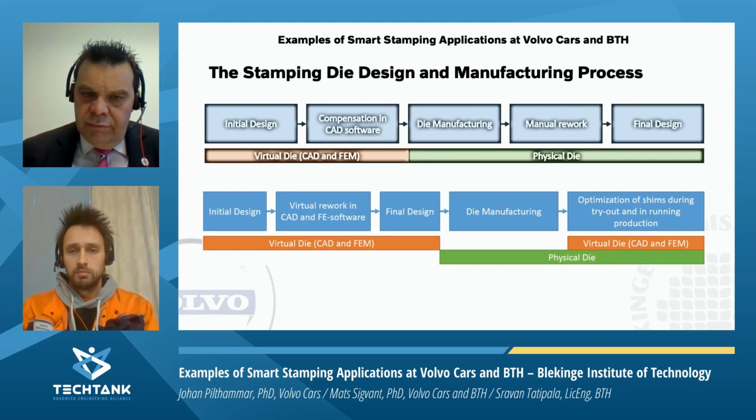And this manual rework, a big part of that is that everything is bending a little bit. So after tryout, we have some die surfaces that do not look exactly as they did in the final part in the CAD software.